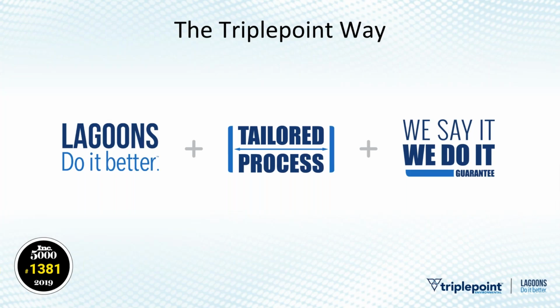And as these operators and engineers of these plants are being told that you have to hit phosphorus, or you have to hit nitrogen limits, the conventional wisdom is you've got to go to an activated sludge plant. And as the lagoons-do-it-better people that we are, we say, no, you don't have to. A lagoon simply wasn't designed to treat phosphorus, or it wasn't designed to treat nitrate, but it can do it. We just need to modify it to do so.